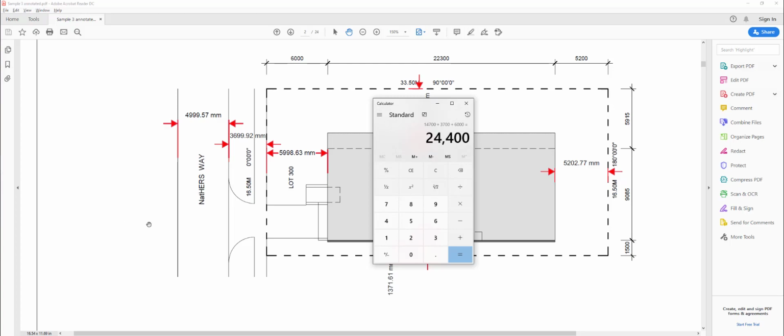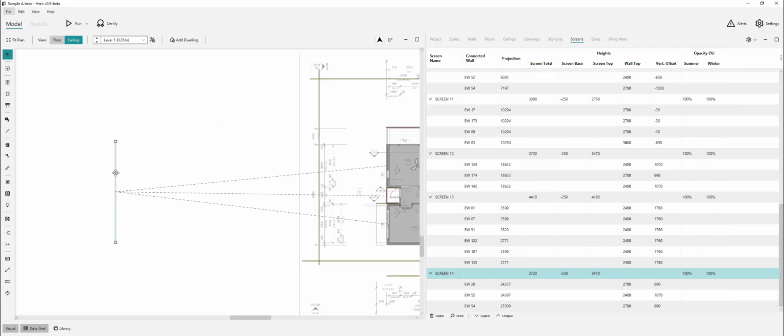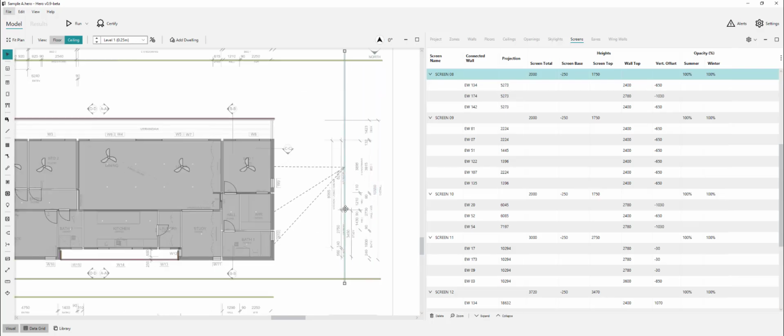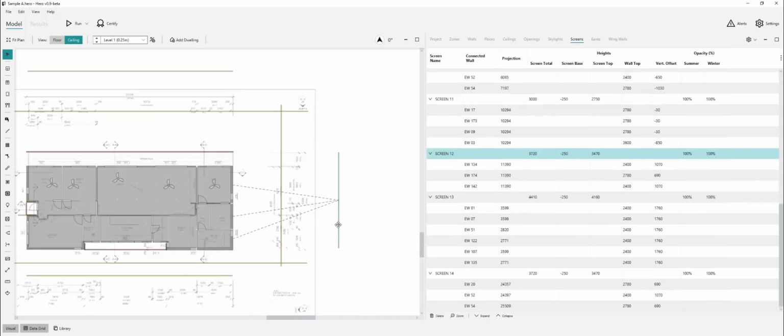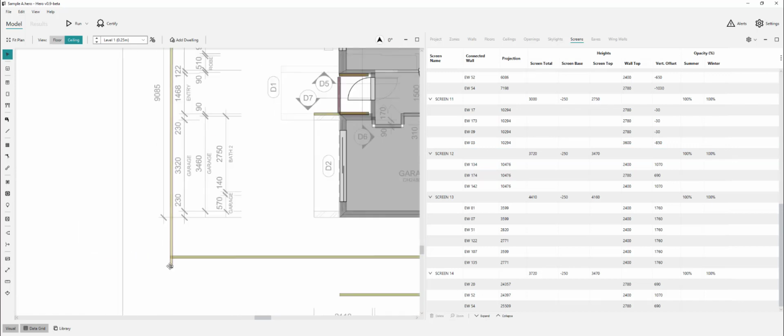So at that point, you'd be considering whether this really needs to be modeled. Our eastern fence is about 5.2 meters away, so we'll move that one in, and this one will be then double that, 10.4. And now we can kind of clean up these fence edges.